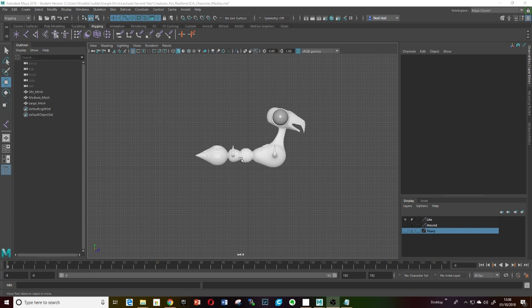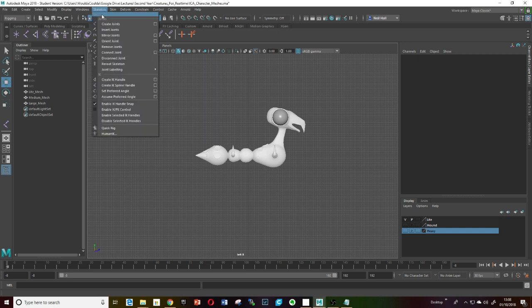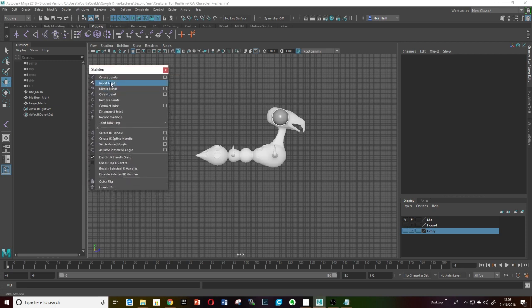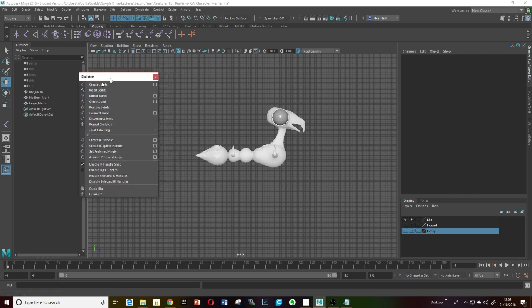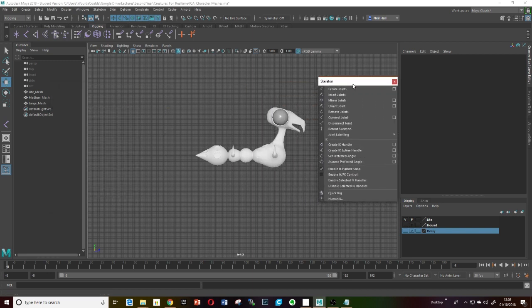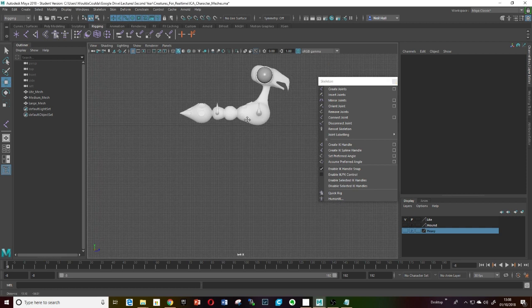So the first thing we want to do is get the root bone down to tell Unreal that this is the center of the object, and from then on we can start drawing some extra parts and the actual skeletal structure itself. If you want, click on the skeleton and just break off the tab using this dotted line here. You might find that these are a bit handier to have nearby, rather than going to the menu all the time. Just have a play with it, get used to how it works before you get stuck into actually creating the bits themselves.